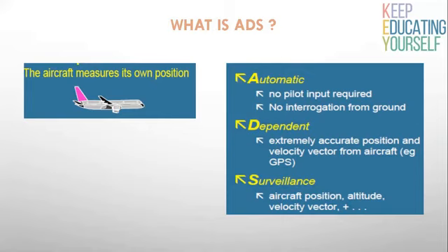The ADS system is basically a data link system that transmits data from the aircraft's onboard navigation system about its position, altitude, and intentions to the ground system. Dedicated ADS-B ground stations can receive the broadcast and relay the surveillance information to ATC for precise tracking of aircraft. Other proximate aircraft can also receive the broadcast.